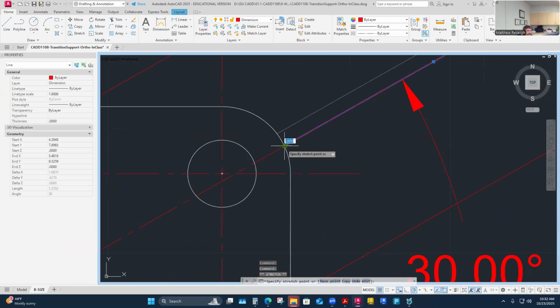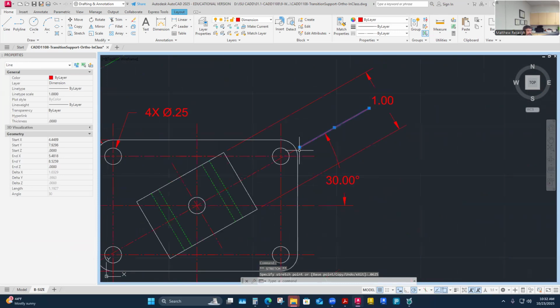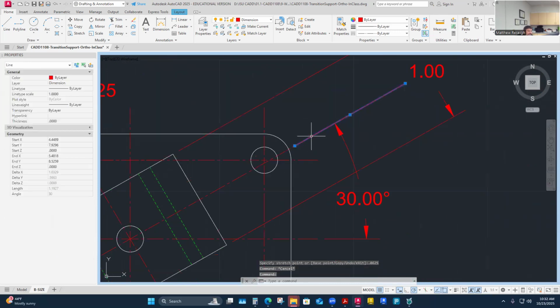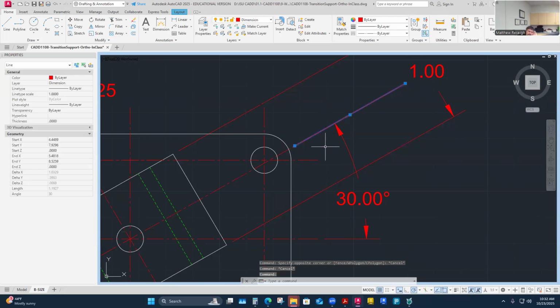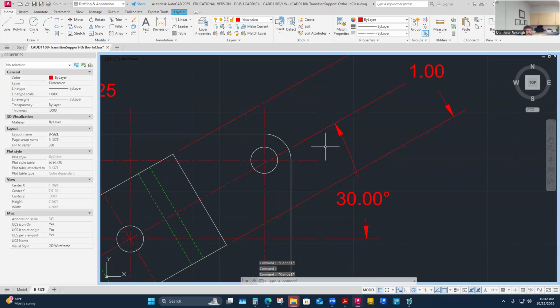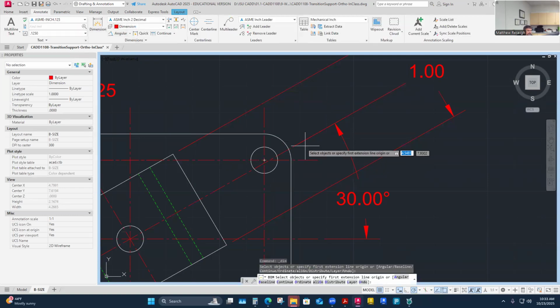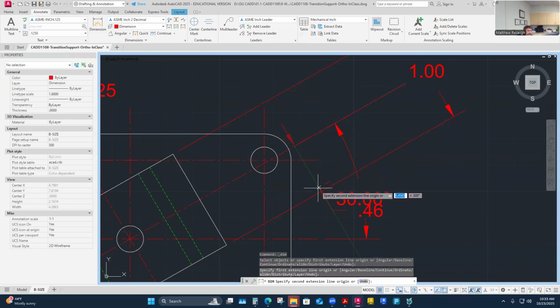Technically, this should break away by a 16th. This is a small detail, and the center line is going to overlap that anyway a little bit, and you may not even be able to tell that I did or didn't do that. But now this gives me a place to potentially pull a dimension in alignment with, right? Dimension this from here to perpendicular to here.